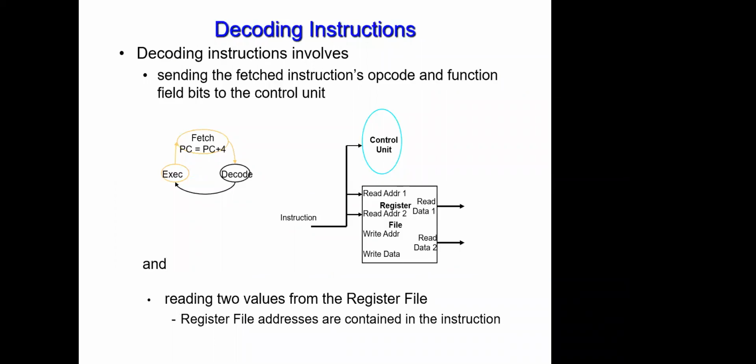So going back to the data path that we have already explained earlier, with each fetch I have to update the program counter to the program counter + 4, and then I have to decode, and then I have to execute. So I will take my instruction from the instruction memory and decode it. Why? Because from the decoding, I will know which type it is, R type, I type, J type, and whichever type it is, I need to know what exactly I have to do.